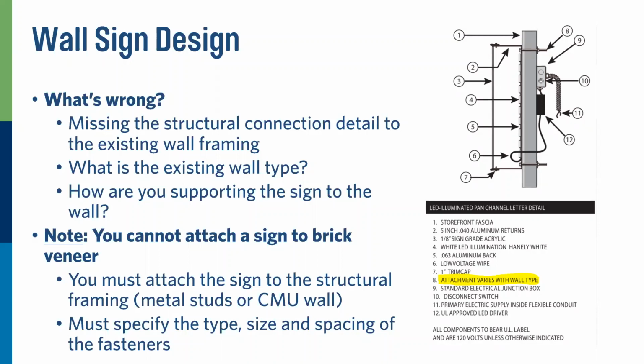So I can pile it up 100 feet high, and if I had a perfect load straight on it, it would work just fine. But that's not what we're designing for. I'm designing for that lateral pressure, the in and out movement of what that sign does on that wall. Imagine a 10-foot wall just standing here by itself and I were to push on it. I could very easily push that wall over, if it didn't have any type of straps or brick ties or things like that.